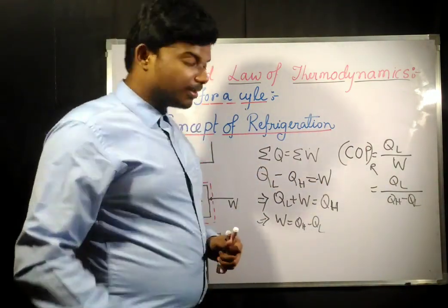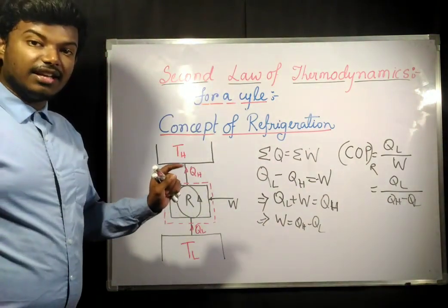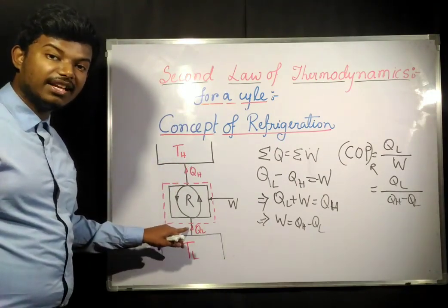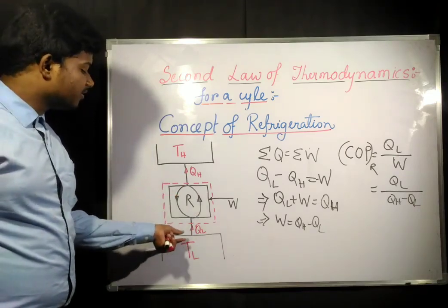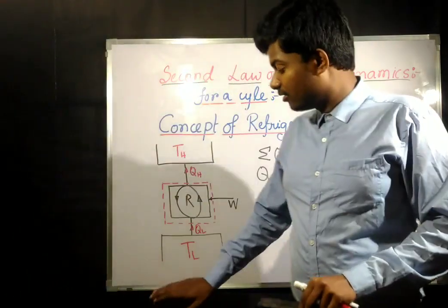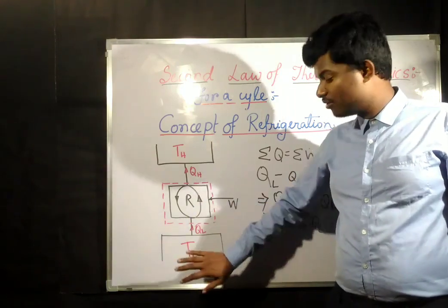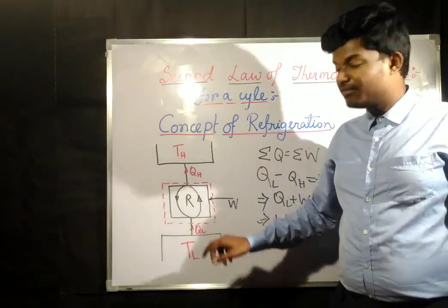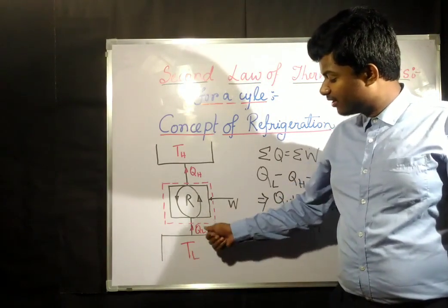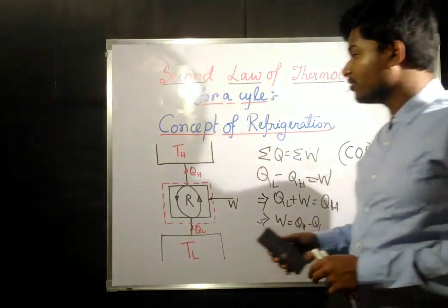Now, another concept is the refrigeration effect. Refrigeration effect is what? This QL is going to be the refrigeration effect. That means whatever heat you are going to take out from the cold region, or the region where you need to maintain a temperature lower than atmospheric temperature, is known as the refrigeration effect. This heat which you are taking out from here is very important for the concept of refrigeration.